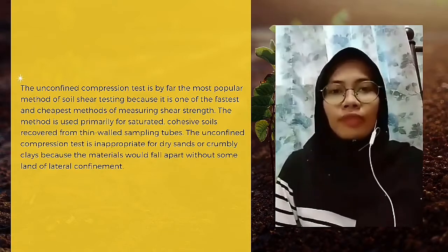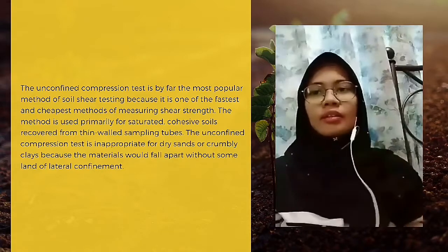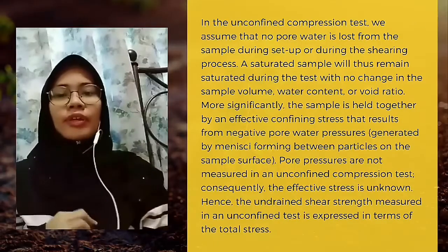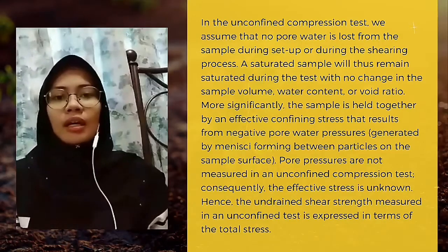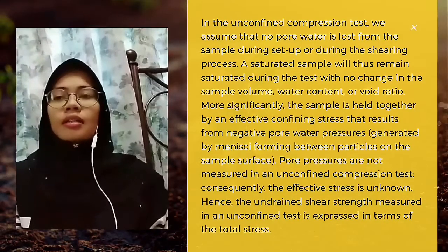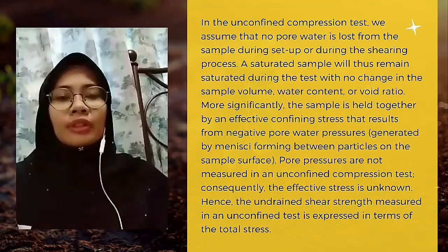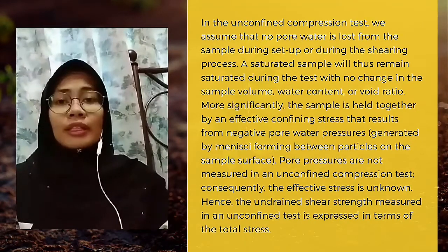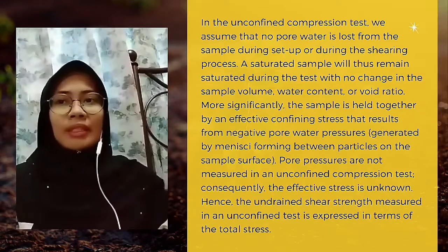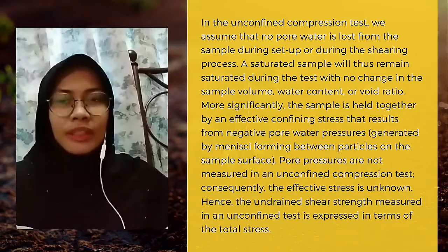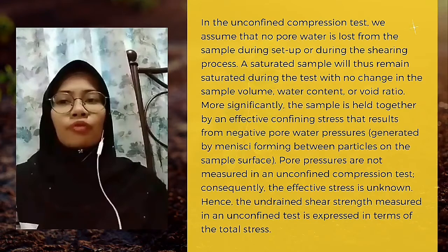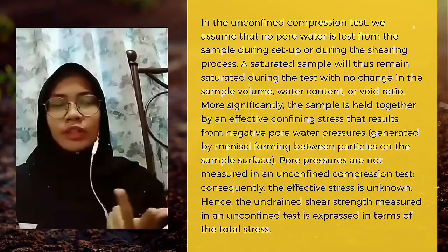Okay, in the unconfined compression test, we assume that no pore water is lost from the sample during the setup or during the shearing process. A saturated sample will thus remain saturated during the test with no change in the sample volume, water content, void ratio.